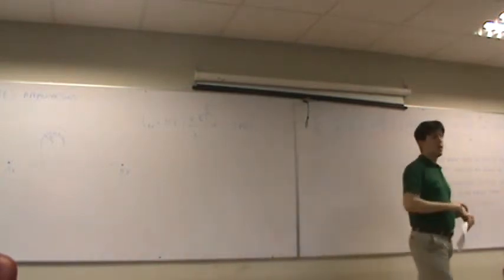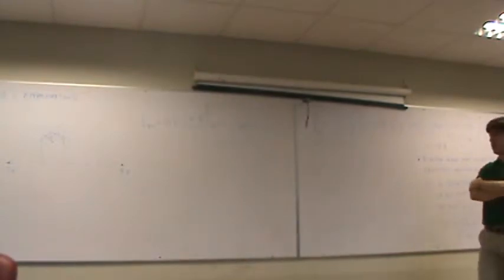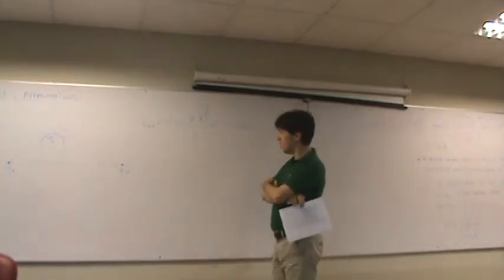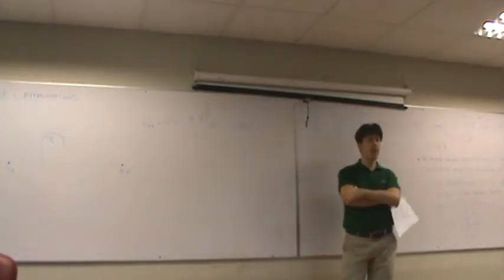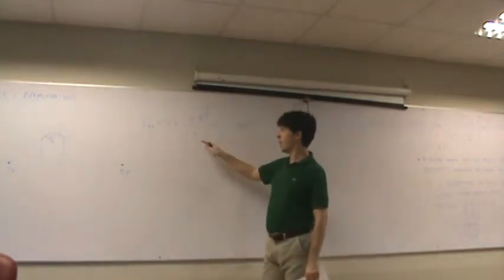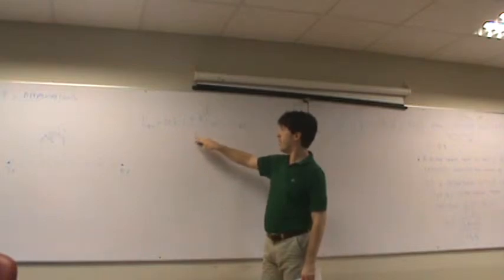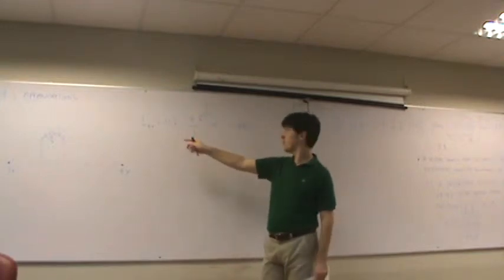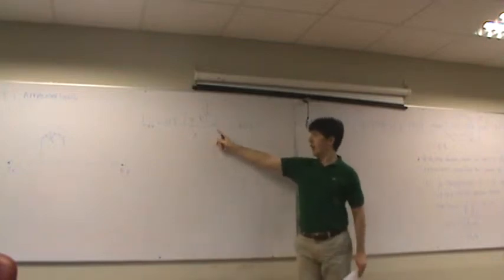Those are empirical equations, so we cannot try to derive them from electromagnetic theory. They are approximating equations that work well, but you lose the physical meaning of the equation. Nevertheless, those are extra dB of attenuation, extra losses, that depend on lambda, on the radius of curvature of your round obstacle, and on the angle alpha.